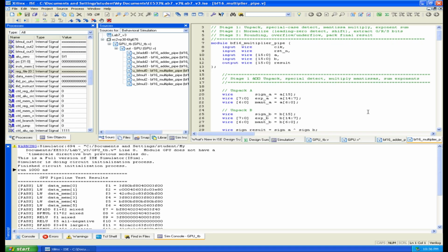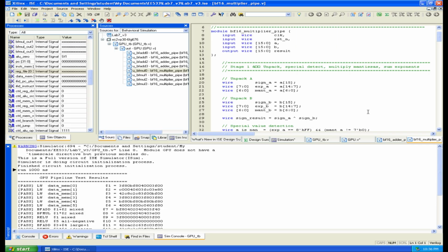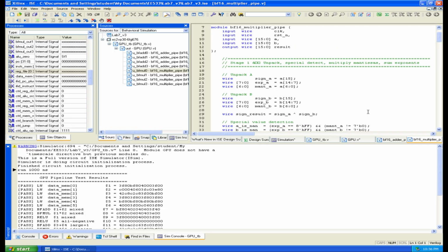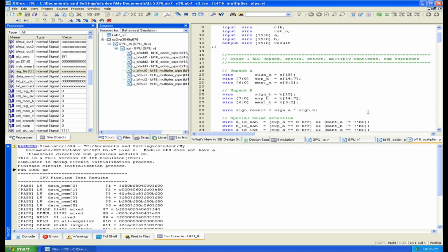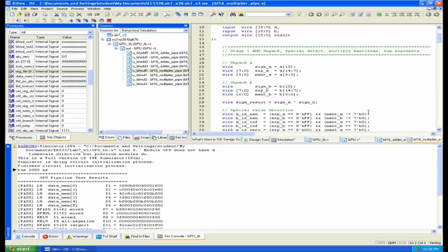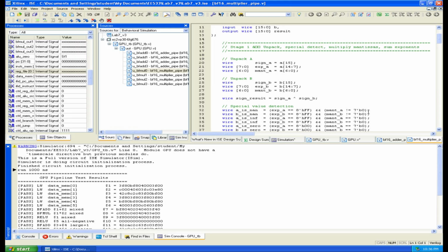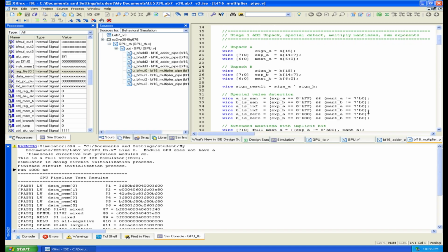The multiplier is less complex because of the structure of bfloat16. So we divide our multiplier and the adder into 3 stages. So this part is we need to prevent some problem when we do some onboard experiment because the clock is limited, so we cannot do a very long critical path in here.